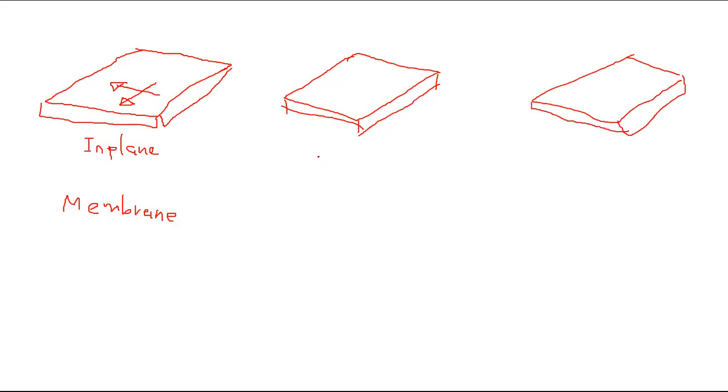For plates, you will have only out of plane stiffness. Not in plane. It cannot take in plane forces, but it can take out of plane bending. So the perfect example is a reinforced concrete slab. If this is the side view,